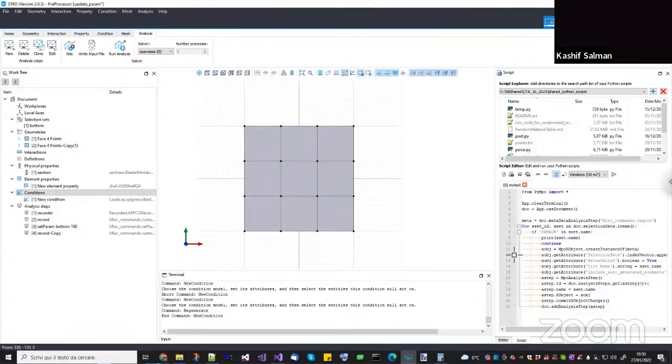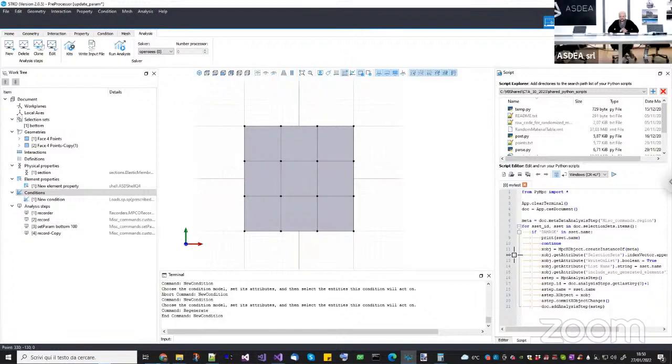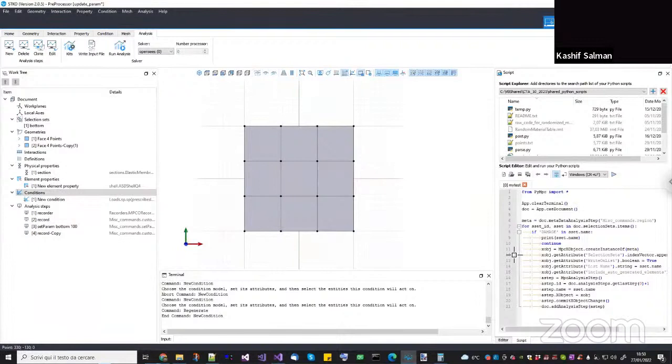Basically, my problem is dealing with the non-structural component, more specifically the cabinets within a structure at different floor levels, and more specifically in timber structures. So the problem is when I want to model this in any platform like Abaqus, SAP, or anyone, it becomes a complex eigenvalue problem. If I consider the damping of the non-structural component and the damping of the structure, they are different from one another. So the problem turns out to be the non-classical damping effect first.